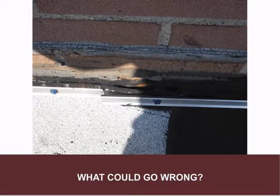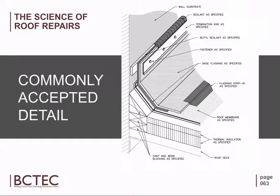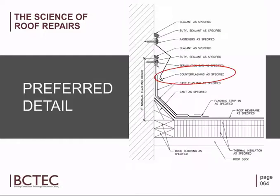So we see the sealant being failed. Again, a close-up of the detail here where we've got that base flashing coming up. We've got the termination bar secured into the masonry wall system and the sealant. Now, Craig, in more of a strategic repair scenario, rather than replacing just that sealant and relying on that bead of sealant, what might you do in a strategic repair?